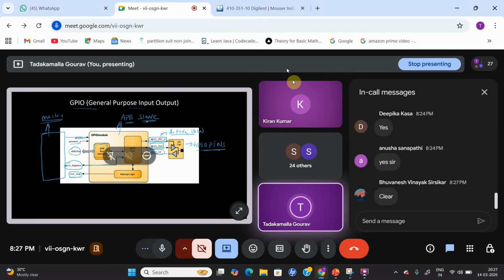It's a direct pin. So we can directly access the GPIO pins without using the APB interface. We have that particular control, but we will face some timing issues if you're going to have direct control. That is generally recommended if you're going to drive some basic LED control or LCD control. But if you're trying to access your GPIO pins for establishing a connection like a UART connection or some I2C communication, then it's not a recommended option.